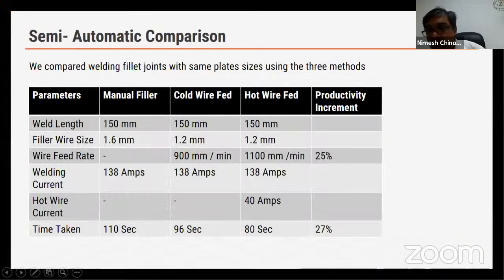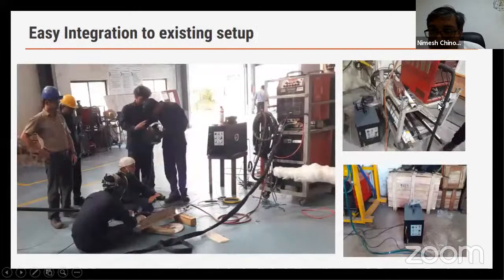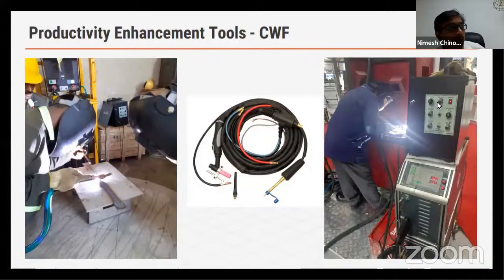So if you look at the wire feeder in the image on the left, there is a part which says you can have an increased speed control. If you calculate the volume of the mass of the 1.2 mm wire and multiply that by the speed, you will get the volume of deposit. While the welder is welding, if he wants a heavier bead thickness, he could increase the wire's feed rate. You can set the feed rate right from 0.1, which is about 10 millimeters a minute, to about 5 meters a minute. In manual, you could feed at that kind of rate if you wanted. This is the wire speed knob here.